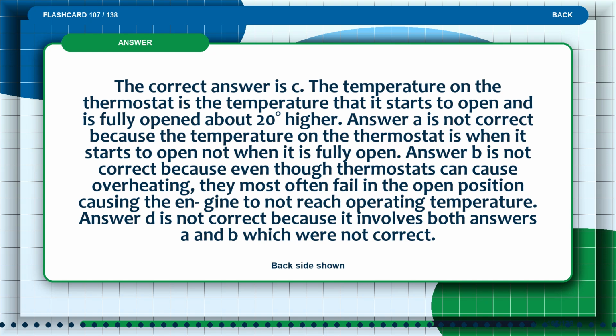The correct answer is C. The temperature on the thermostat is the temperature at which it starts to open, and it is fully open about 20 degrees higher.